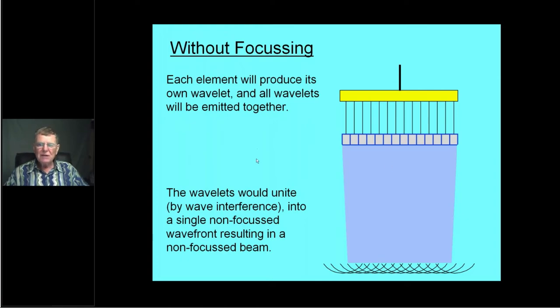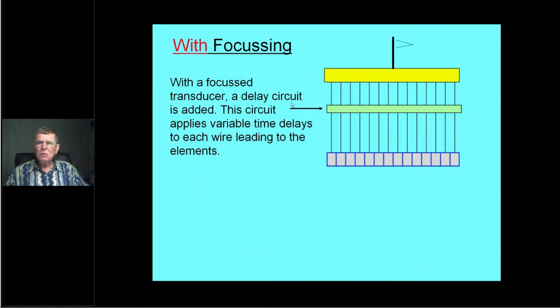Okay, so we've got a non-focused beam, but we want to focus it. So what the designers came up with is that they added a circuit into the beam formation circuitry. It's a delay circuit. Now I'm showing it just here within the transducer itself, but all of this will be happening within what's called the beamformer.